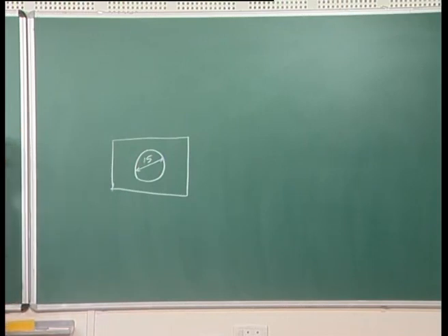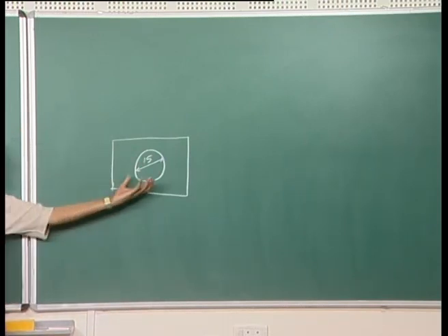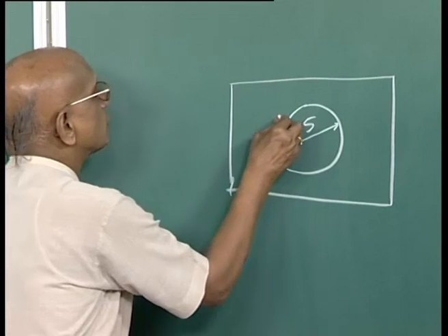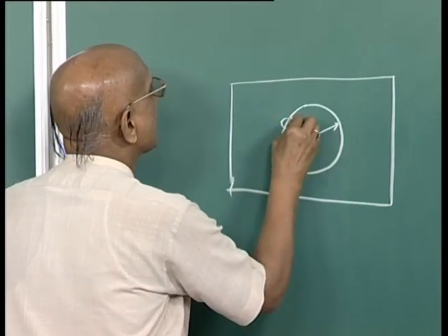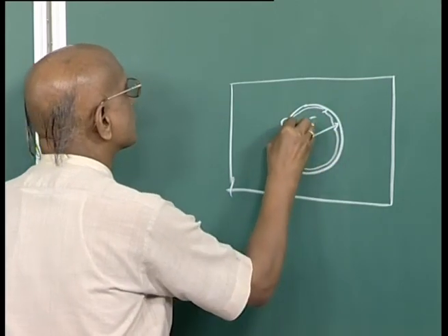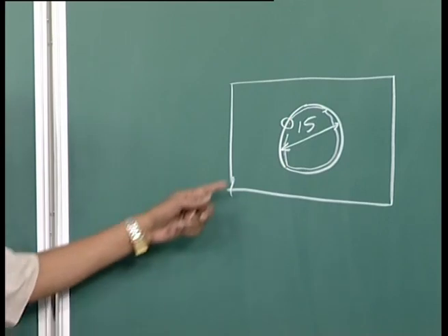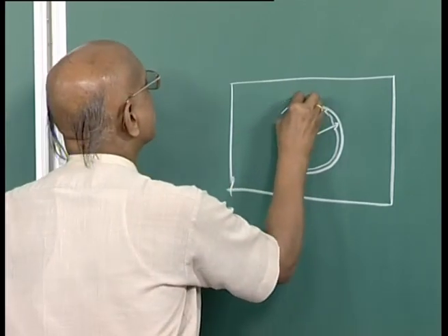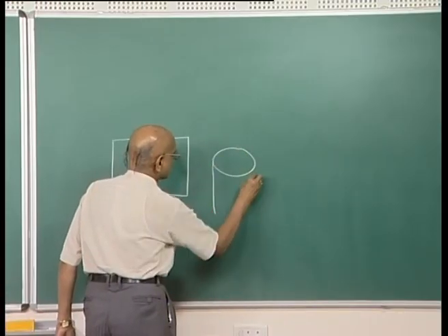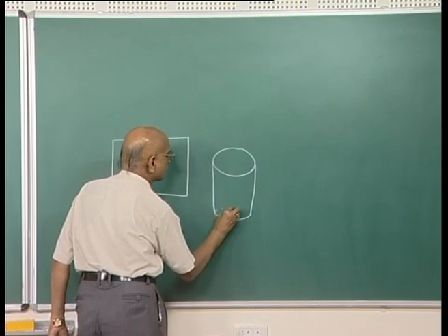then there is no sense in melting and vaporizing the whole of the material of this particular 15 millimeter diameter and depth equal to the depth of the hole to be drilled. So, the best way in such cases is you do the trepanning operation. That means you cut the material along the periphery of the hole being drilled. So, after machining, once you have moved it through the whole length along this particular periphery by trepanning operation, then what you will get is this particular solid material that has come out of this.